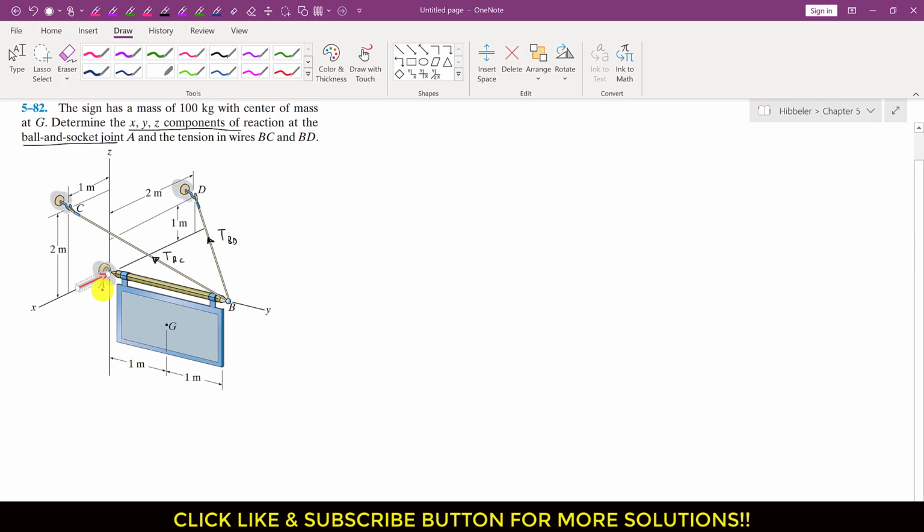We are required to determine the reactions at this ball and socket joint. So let's say that here we have the AX reaction, which is acting in the negative x direction. Here we will have the AY reaction, acting in the positive y direction, like this. And we have a reaction in the positive z direction, let's say this is AZ. So we are required to find the magnitudes of AX, AY and AZ, and the magnitudes of this TBC tension and this TBD tension, right?